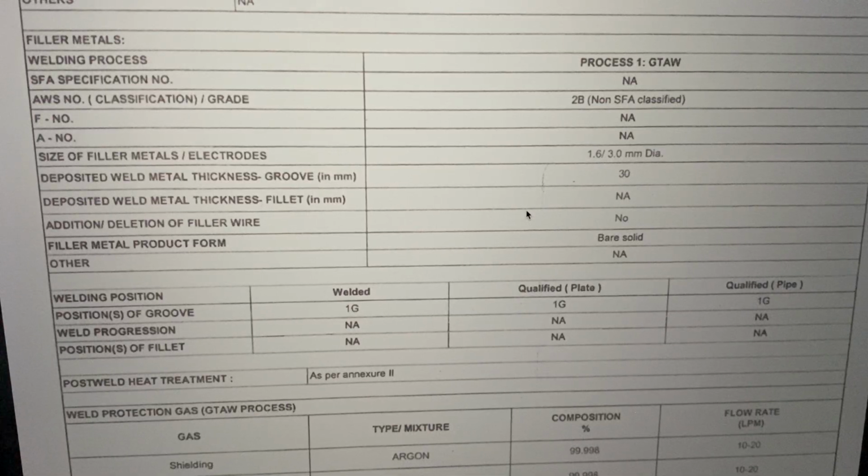If it is a dissimilar joint, then A can be completely different from F. That is, the weld chemistry could be 309, which is highly austenitic stainless steel, but your resultant chemistry may or may not be highly austenitic like 309, which has 20-25% of chromium and nickel; it can be 18-8.